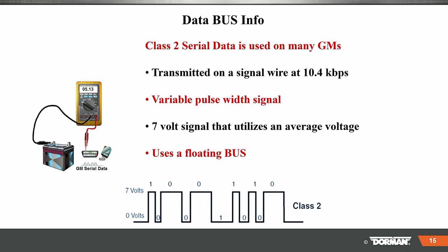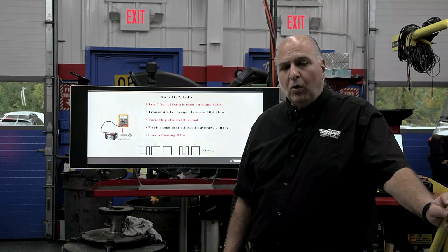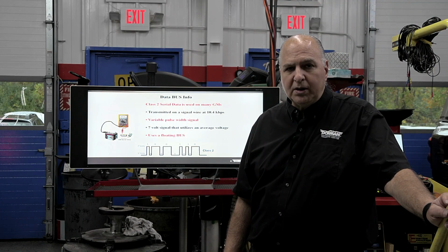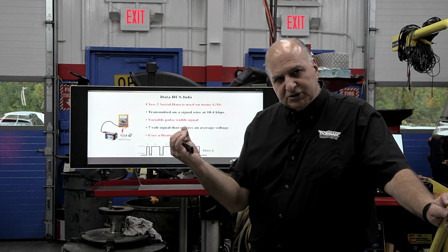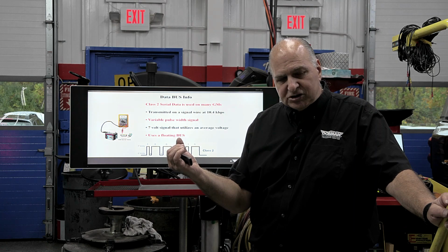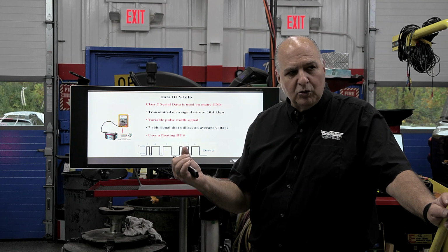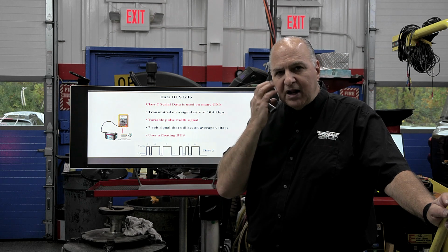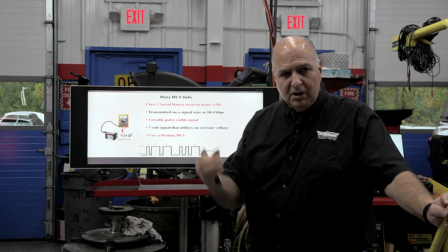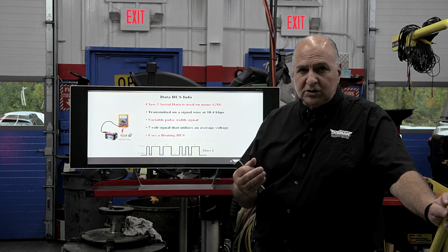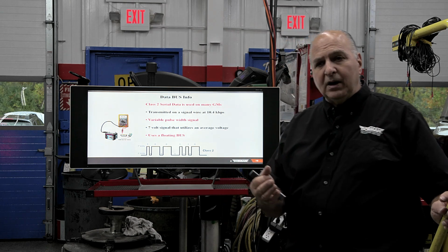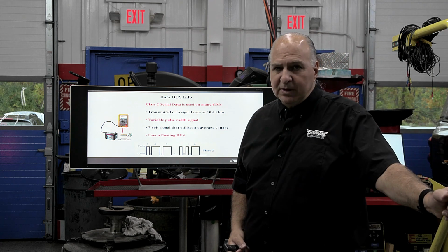Questions? What's your opinion on the solder heat shrink combos? We use the solder heat shrink all the time. We use a Milwaukee gun. We used to have the wired one, but now we use a Milwaukee battery operated one. You got to use the deflector shield. Make sure you go on the solder first. And it's a good idea to have some of that aluminum type of foil. You can get it in Home Depot. It's insulation, because you do not want to take a chance of melting any of the wires. So we use it all the time. We buy the stuff through Napa and other companies. And I think that's the best way to go nowadays.